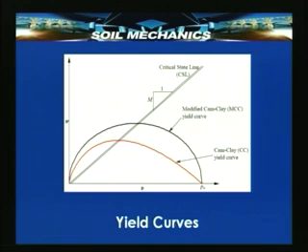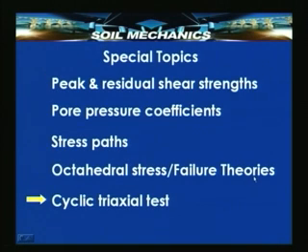So, this point or this point will represent a situation of large unlimited deformation as in the case of liquefaction, and this can be predicted reasonably well using the Cam-Clay or the modified Cam-Clay model.